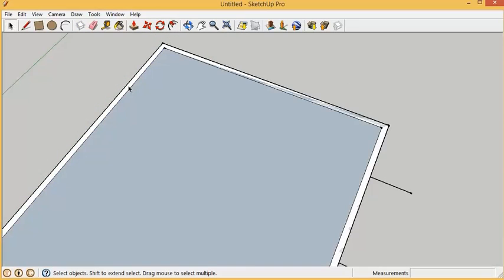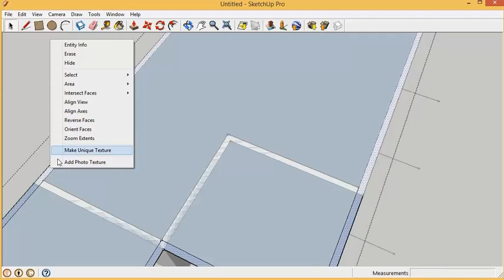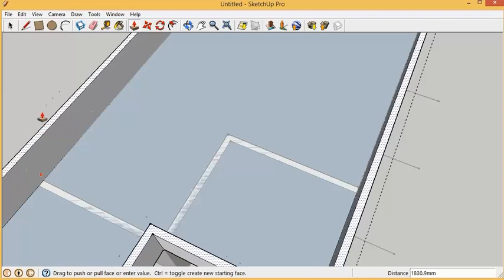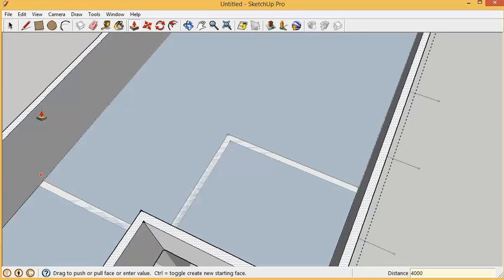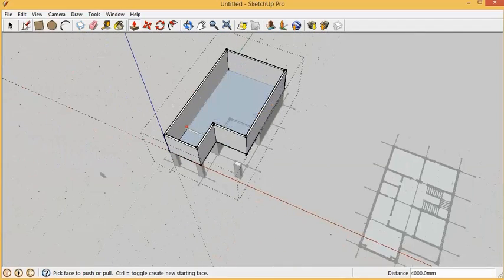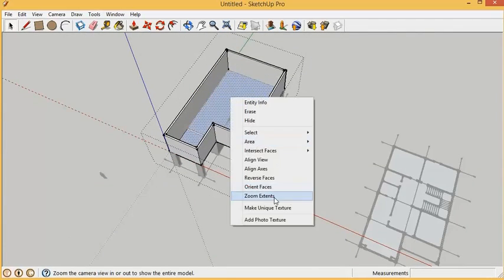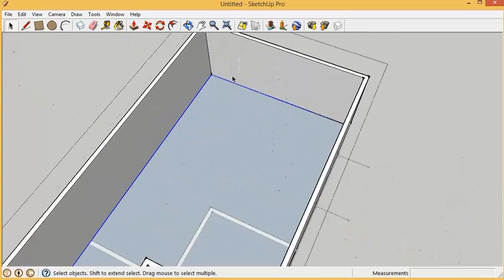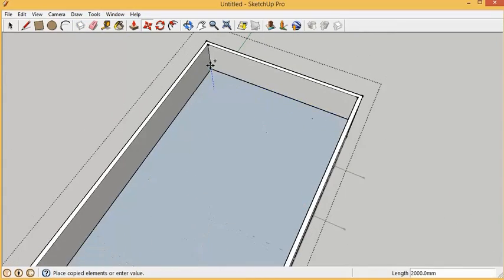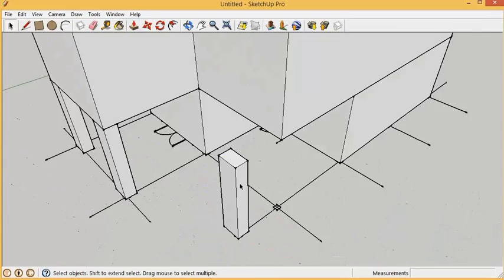This is an example that SketchUp has provided. Now I can actually start, and our SketchUp Pro course will tell you how to do that, but this really is just how to use it. So if I want to change my spacing, which was 5 inches, I can change it, and now my pickets are further apart. If I want to change that to a lower number, I can, and then left-click a third time.